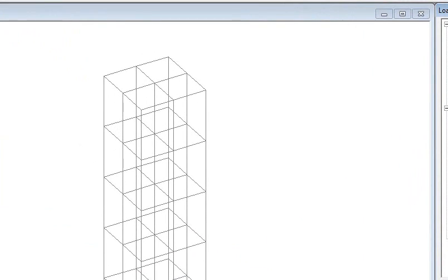Now we have already created the various load case details. The next step in the wind definition is different from the other two, the dead load and live load: go and create the wind definitions. That is, we are defining the way in which the wind will act, because the wind acts in various ways in various parts. Say in a coastal region the wind intensity is a little higher and the safety feature is a little different. You can always refer to IS 875 part 3 for the wind load definitions.